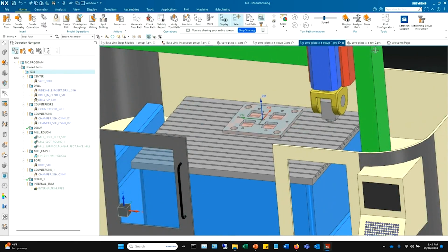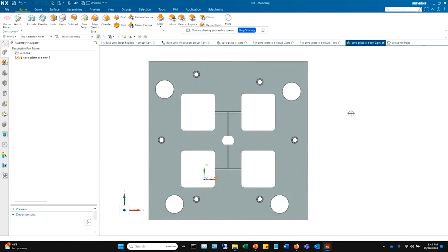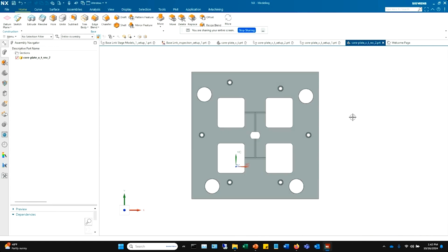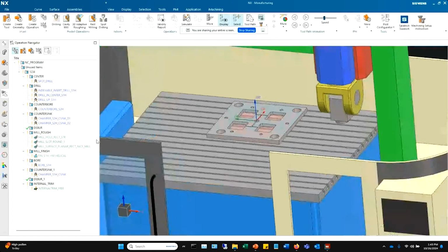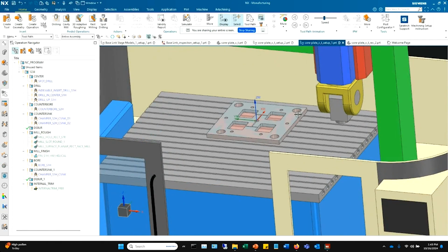So now here is the most important piece. So many times you could have just submitted your project as complete, and then they send you a revision. And then how do you recover from a revision or engineering change order? Most all of your softwares have no connection between CAD and CAM. So the best you're able to do is make a new program, Rev B, with the new part, and then copy operations like this to the new one, and then open each one, select the new geometry.